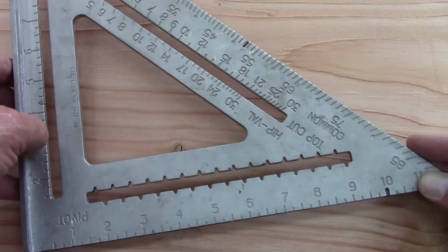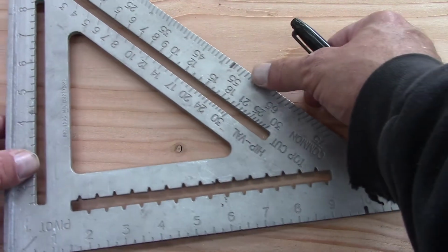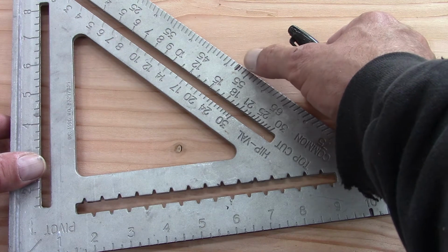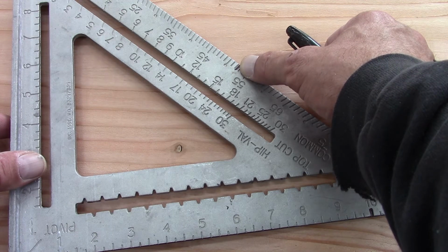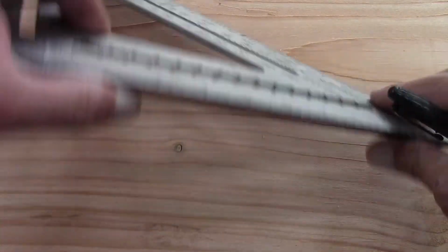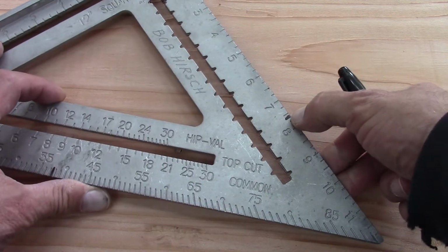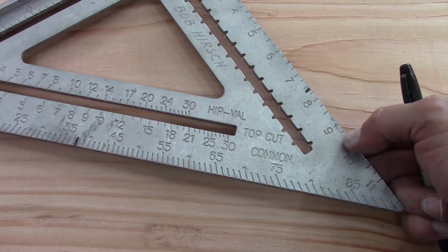However, what I like to use is a roofer square, and what I did was I put a black mark on the 10 inches on this side, and 30. So 90 degrees minus 35.55 equals 54.45, and so that's where I placed the mark there so that it would give me the right angle. Other side, there's my 35.55 and the 7 11/16 or 5/8 that I need for a rise.